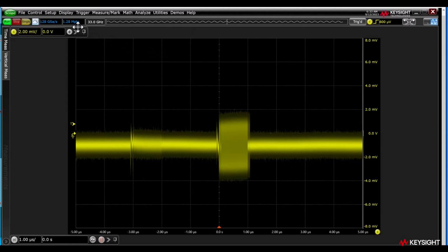That's going to take that 128 gigasample per second time volt data and convert that into much lower sampled IQ data, sampled just fast enough to be able to discern this modulation that's on top of these pulses, and that these pulses actually are creating versus it just being a carrier.